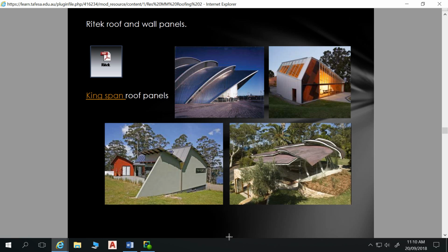But that limitation, the fact that that's only R 2.5, means you can't just go, all right, yeah, let's use SIPs for a roof on its own in a residential application. You'll still need to batten that out, and you'll still need to provide insulation on the underside of that to bring it up to 4.1 or 5.1 or so. So you've got additional expenses involved in that, and so this ends up just becoming too expensive to do for roofs. I think it's unfortunate, but that's yeah.